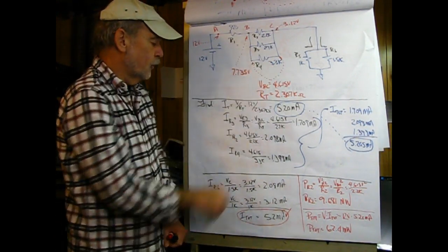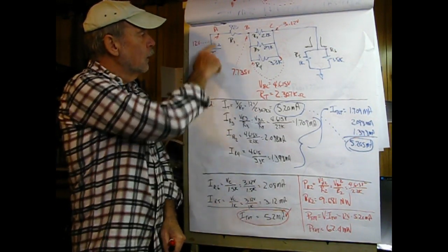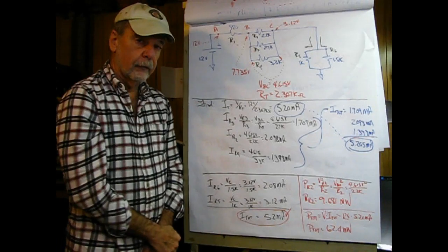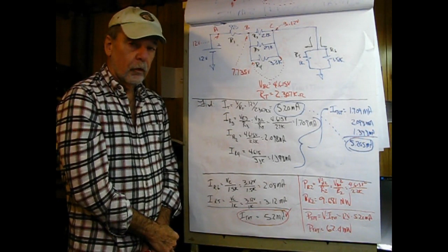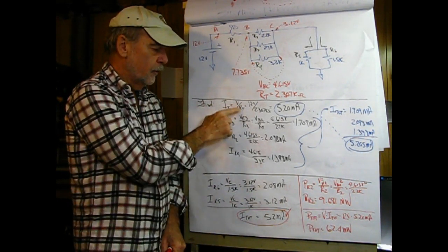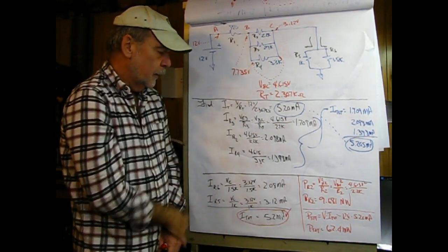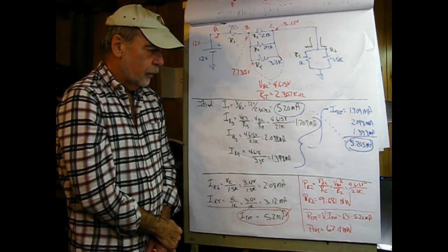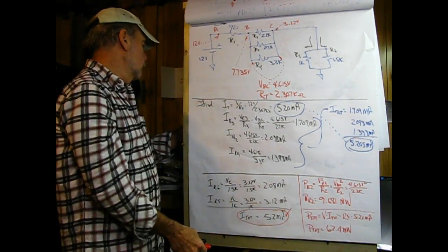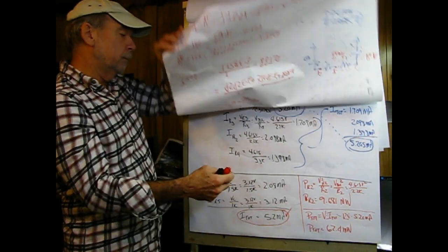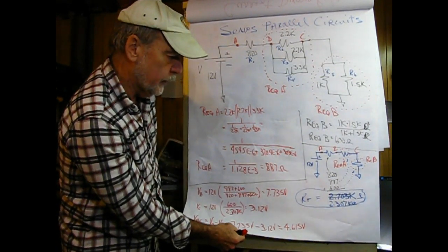and I've just redrawn this diagram, let's find some circuit parameters, and the first is going to be the total current flow, which would be this current right here flowing out of the source into our resistive network. So this is just a matter of Ohm's law. I total would equal V divided by R total. That would be everything to the right of my hand. And 12 volts divided by R total, 2.307 k ohms. And let me see, I didn't mention that number before, so I'll go back, find out where that is. Here we go. R total is 2.307 k ohms.